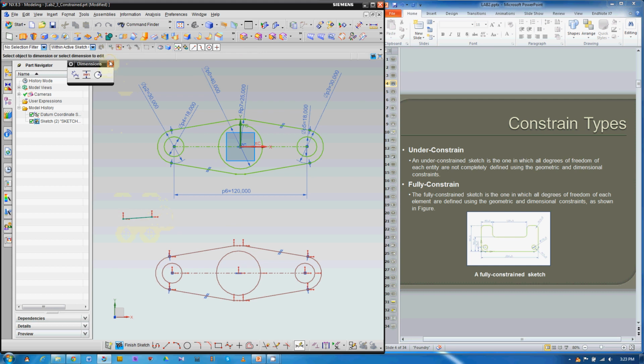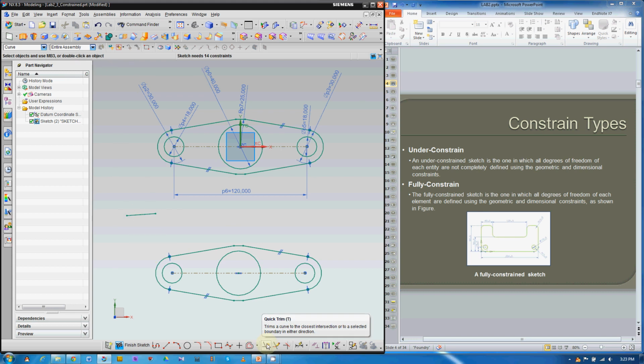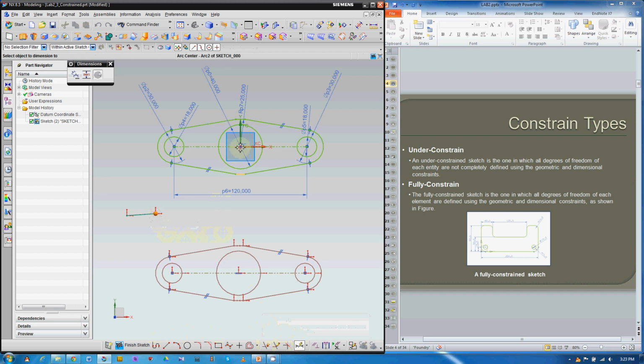If you try to move this, you will be able to move this line. You can move x and you can move y. I'm holding down the left mouse button and dragging this line. What if we constrain the x direction of the degree of freedom? We can give this a dimension like so.